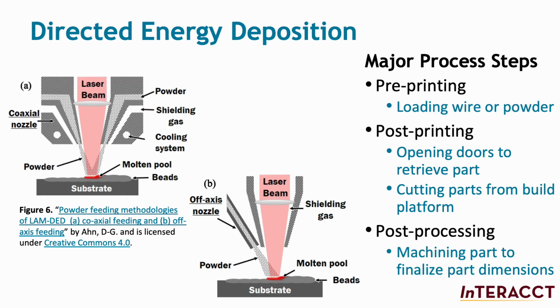Directed energy deposition uses focused thermal energy produced by a laser or electron beam to fuse melted materials as they are deposited. The material is a metal powder or wire. This process produces near-net shape parts, meaning that the parts produced are very close to the desired final shape and size. This technique is attractive for its ability to reduce production costs and time associated with finishing steps. Unlike the other AM processes, with DED, multiple materials can be deposited simultaneously so that functionally graded parts can be made. Because of the 4 or 5 axis motion system that positions the deposition head, the process is not limited to horizontal layers, making it possible to repair existing parts. This process is also well suited to making large metal parts.